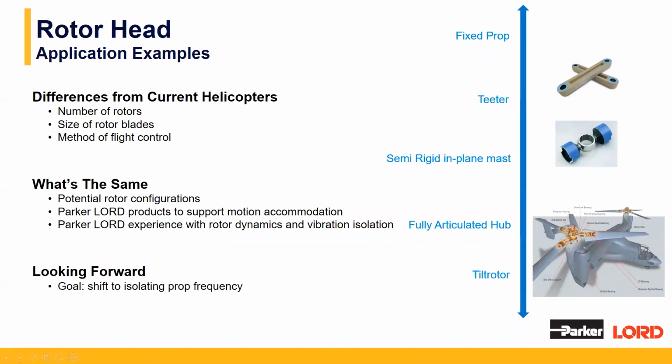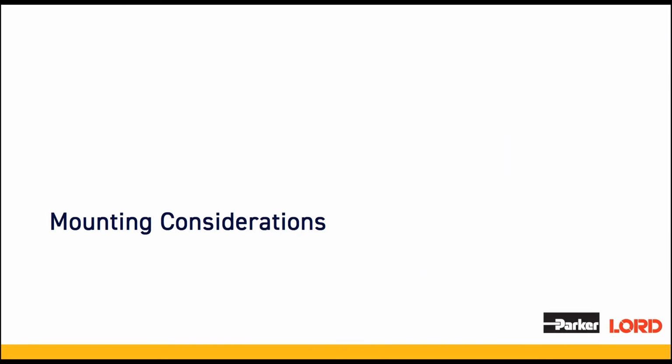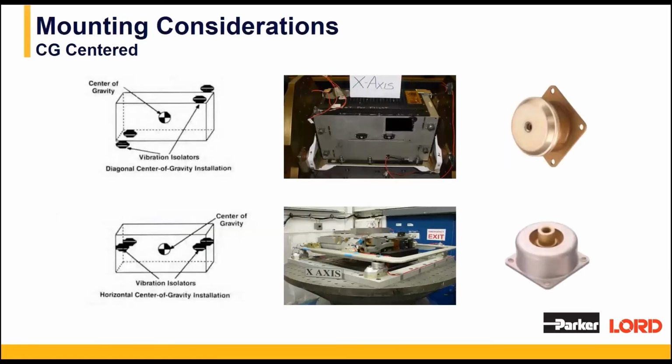And I think you see where I'm going with this. As there's a shift to more rotors, the need for less complex motion of the rotor blades for control authority, the goal of elastomerics may shift from motion accommodation to vibration isolation, and that's why we're talking about it here. Secondly, though it may seem obvious, anything on a rotor head needs appropriate design consideration and time to develop due to the complex motion and criticality of the application. So we do encourage you to engage Lord early to discuss. And we'll continue here to talk about some mounting considerations.